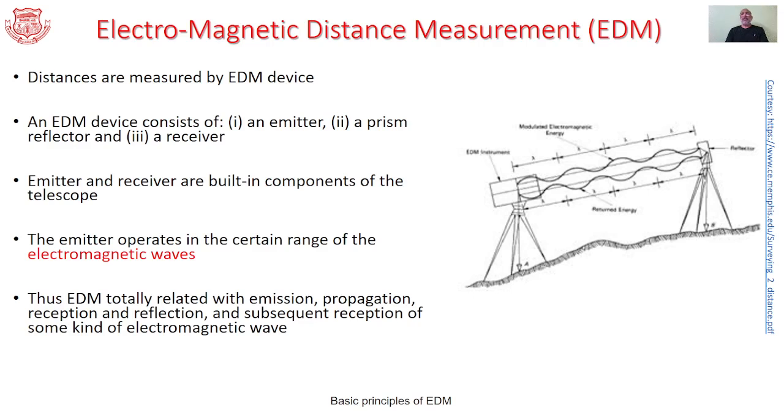The kind of permanent adjustment that we discussed for the conventional equipment may not be in the hands of a common surveyor. However, the methodologies that we discussed, such as the two-peg test, checking the expected relationship of the horizontal line of sight with the vertical axis of the equipment, are valid. So principally, the precautions that a surveyor has to take in order to obtain precise measurements are equally true with the electromagnetic distance measurement concept.